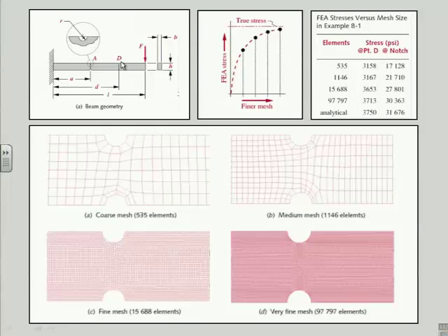So I have 2 points that I'm looking at. Point D is just a point along the beam in some arbitrary location. And point A is in the notch. I want point D because that's the one I can really easily compare to my classical analysis, right? Because I'm going to have to apply a stress concentration factor to that notch, and that could introduce some noise when I do the classical solution.